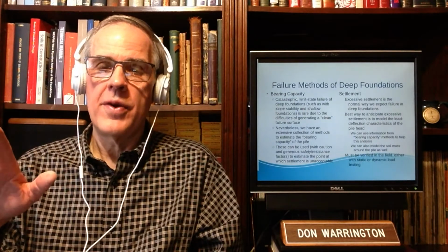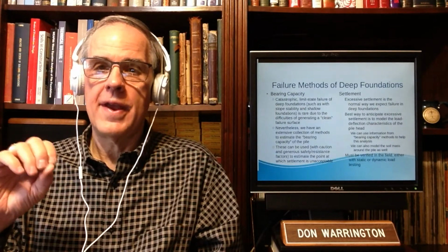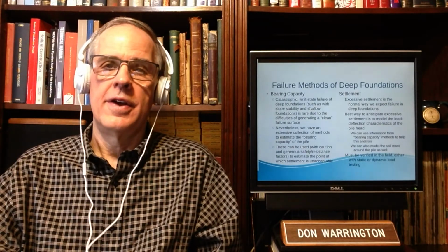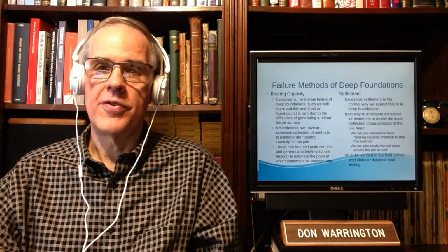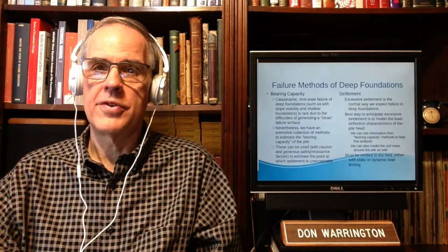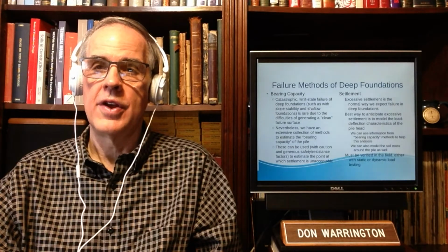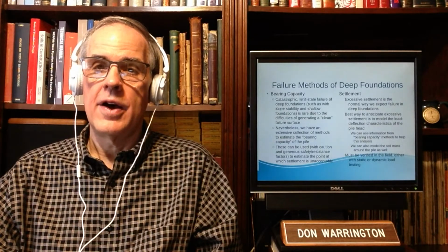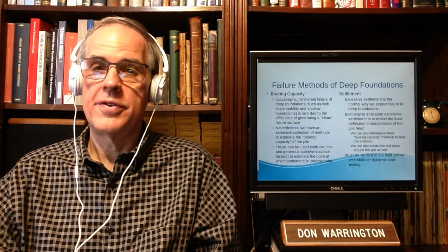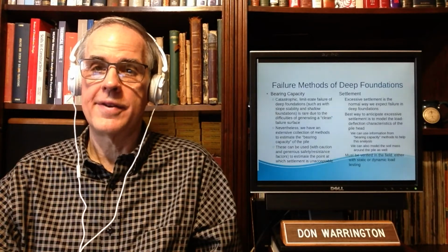As I said, though, the shaft failure is completely different. It's a combination of a frictional failure and also involves to some extent the elasticity of the soil. The settlement of a pile also involves the elasticity of the pile. We're going to get into this when we get to settlement.